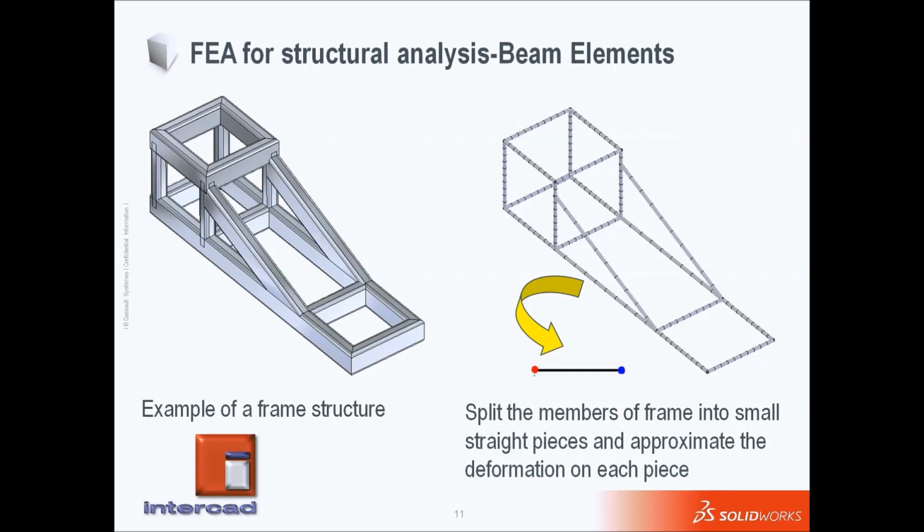Now, it is very, very important to understand which one is correct. If the assumptions of using solid elements, shell elements, and beam elements are correct, we are not sacrificing the accuracy of our calculation. But we have these three options to do the meshing and represent our geometry.